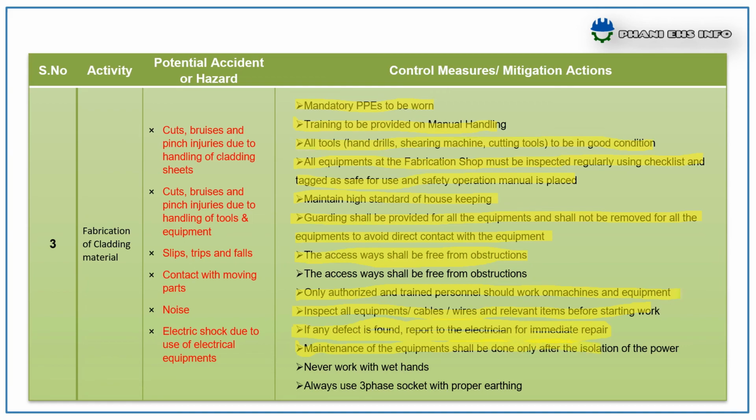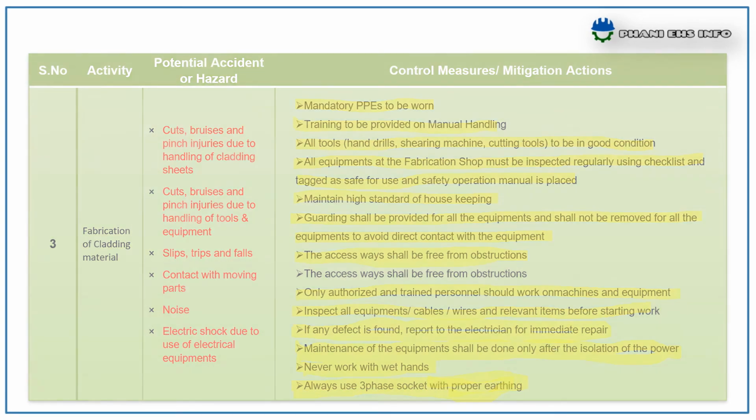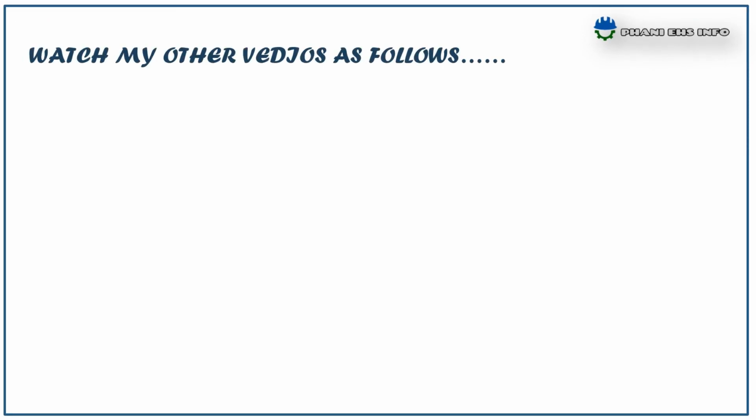Maintenance of equipment shall be done only after isolation of the power. Never work with wet hands, and always use 3-phase socket with proper earthing. This is about the insulation work safety.